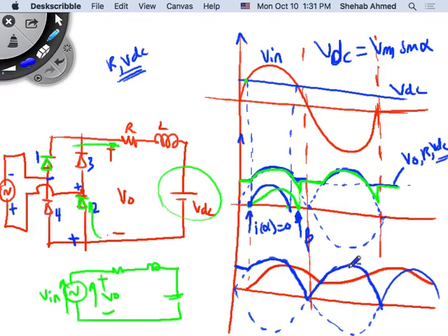So here your voltage is the full wave rectified waveform, but your current does not have a defined closed loop form. So what would we do here? Again, we start from the voltage's Fourier series because it's a periodic waveform that is not sinusoidal. We find the Fourier series for the full wave rectified voltage waveform, and we divide that by the impedance of the circuit at every harmonic to find the current at every harmonic. And then from there you can find THD, power, etc. I think we talked about something like this in the last class.